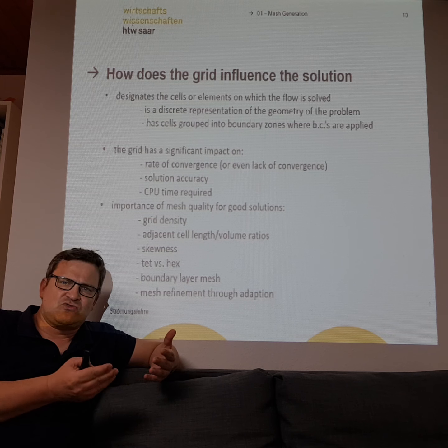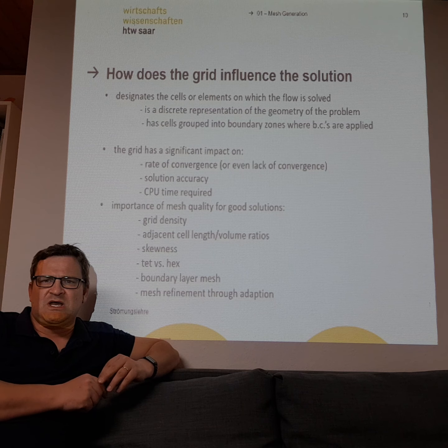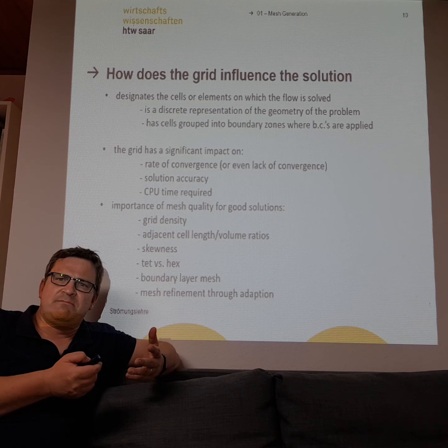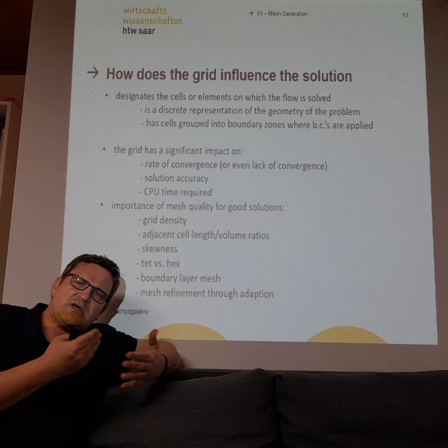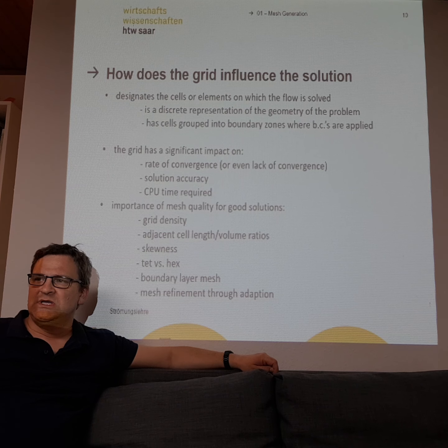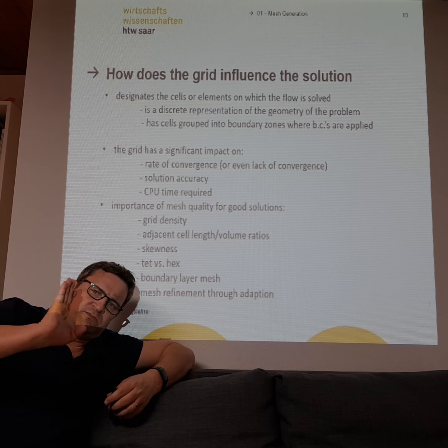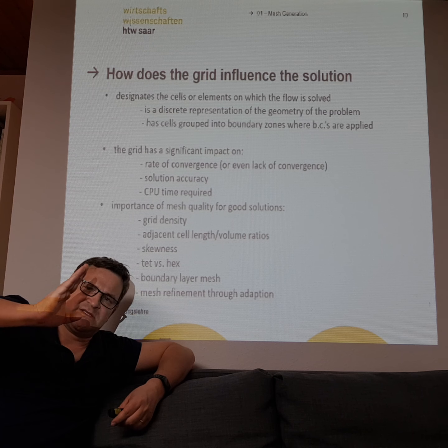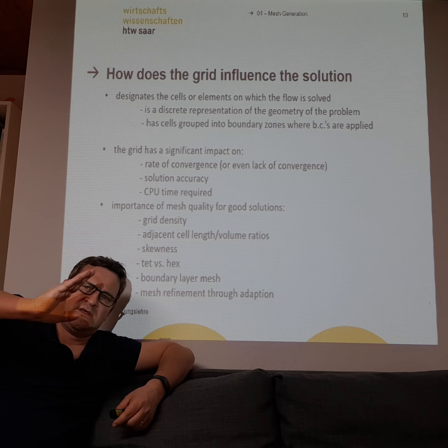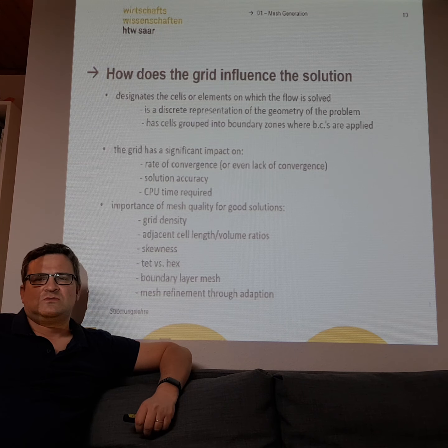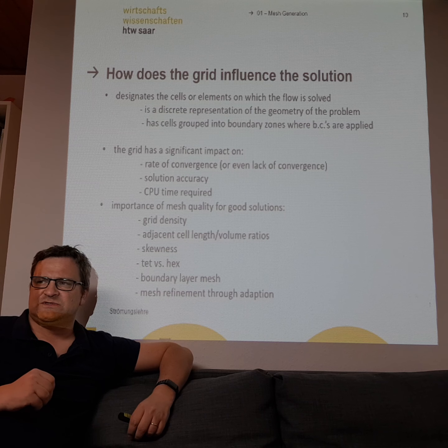Let's look at how the grid influences the solution. I told you, normally the mesh looks like a block, but if it does not look like a block, it will influence your solution. So what is good for the cells? It is good if mass flows into a block at a 90-degree angle. If the face is a bit shifted, or there is another angle between the inflow and the face, you will not get this good quality of the solution.